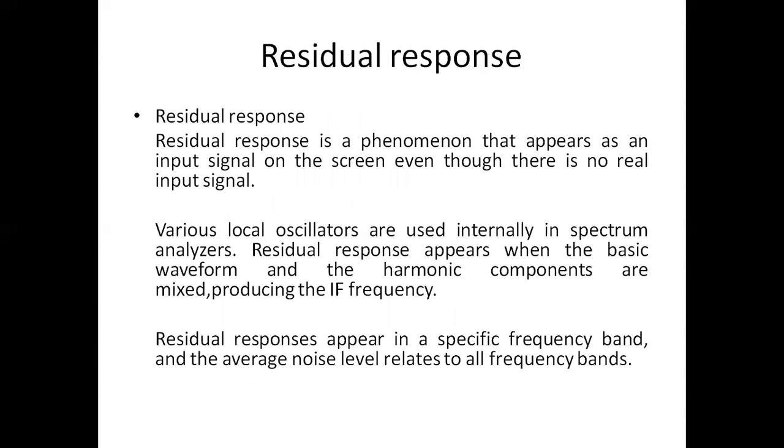The next characteristic of noise is residual response. So it is the phenomenon that an input signal appears on the screen even though there is no real input signal. Since we are using local oscillators in our circuit, these local oscillators will generate some frequencies. That's the operation of an oscillator. So even though we are not giving any input signal to the analyzer, this local oscillator will tend to generate some signals internally. So this may appear on the screen. This is known as residual response.